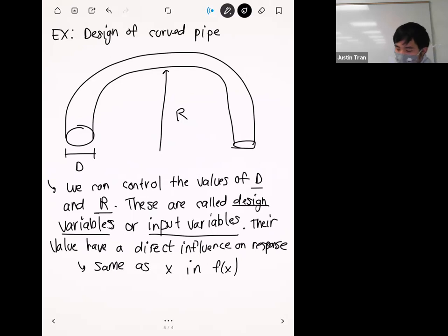And so for this example, I've chosen 2 geometrical parameters as our design variables, right? But your design variables can be even more beyond this too. It can even be the material that you choose. It could be something overall about the geometry too, so maybe an overall bounding box for the geometry. So basically any aspect of the design that you can control, that you can modify, you can have be a design variable for your optimization.